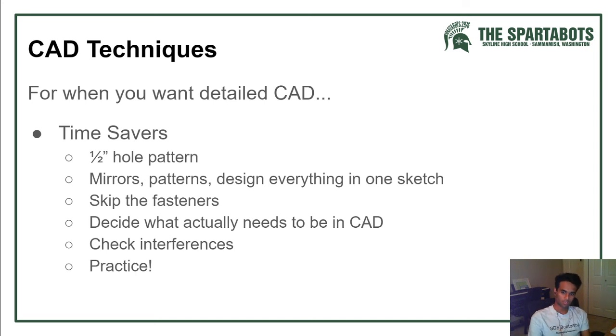Skip fasteners for the first round. You definitely don't need them. Unless you need renders, you don't need fasteners in your CAD. They lower performance. They're just a pain to place. Just decide what needs to be CAD'd and what doesn't, what you can live without.